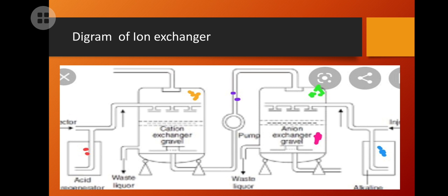So this is made to react with NaOH solution. When NaOH falls onto these negative ions, sodium salts are formed. So we have sodium carbonate, sodium sulfate, sodium nitrate, and sodium bicarbonate all formed, and the anionic exchanger again converts into ROH, and in this way the reaction is restored. Both the anion and the cation exchangers have been restored. So the cationic exchanger is now RH, and the anionic exchanger is ROH.